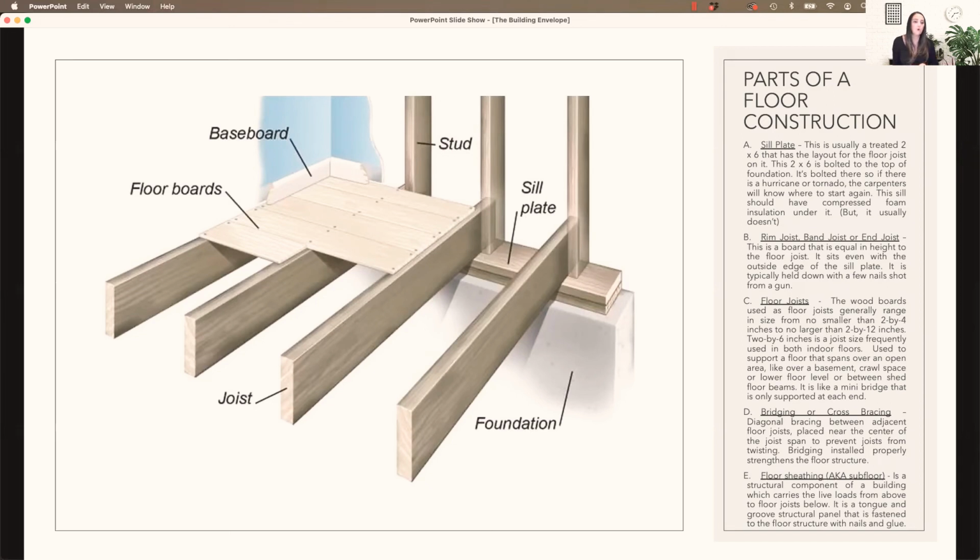So 2x4 would be 2 inches thick, 4 inches wide on the face. So 2 inches by 4 inches, and that's nominal, which means average. The typical dimensions will be just below that. You know, might be 1 3/4 inch by 3 3/4 inch. They can go all the way, like I said, up to 2 by 12.